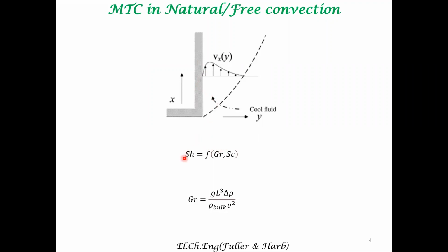So again, in the absence of migration, these kinds of arguments can be utilized to get the mass transfer coefficient, and you can model transport in the electrochemical reactor using such notions. Again, all these empirical correlations have to be tested for their validity.